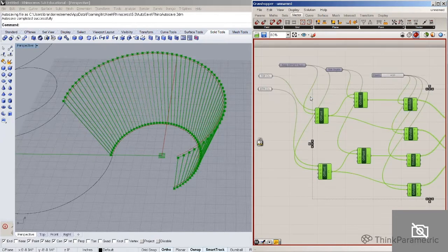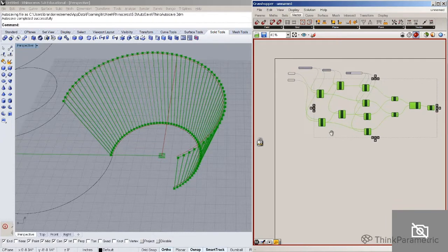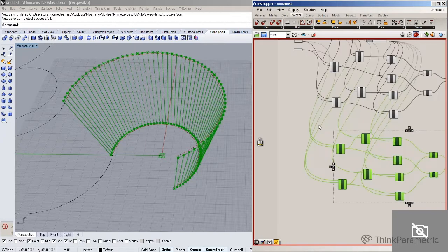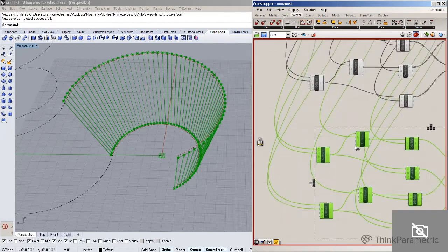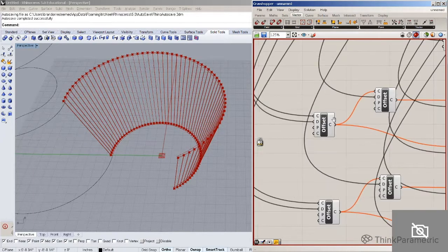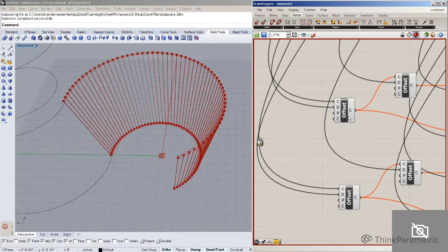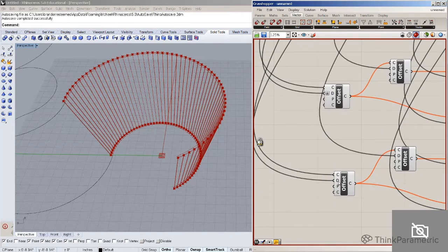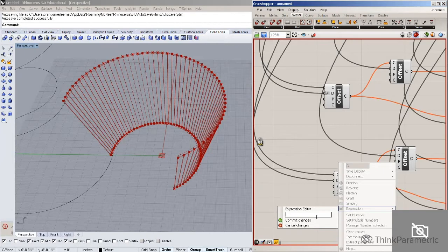And the only thing I'm copying is going to be the operational code, not the main dimensions. And one of the key things that's going to change is basically the origin. And that's going to be these main curves that are offset. The issue is the direction in which it's offset. We're going to change the expression to do that. And we're going to go in the other direction, so we're going to offset negative times the rail offset on both of these on the other side.